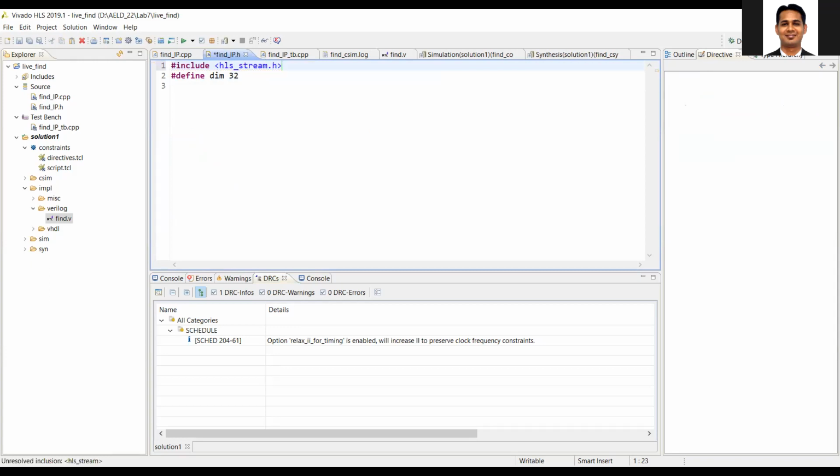In our case, we need only the last signal, but in addition, in the stream interface, there are additional signals like the strobe signal, keep signal, ID signal. So those can all be added, but for today's lab, we will just focus on the last signal. Okay, in a future lab, if needed, we can add other signals. So let's keep it simple. We'll focus on the HLS stream.